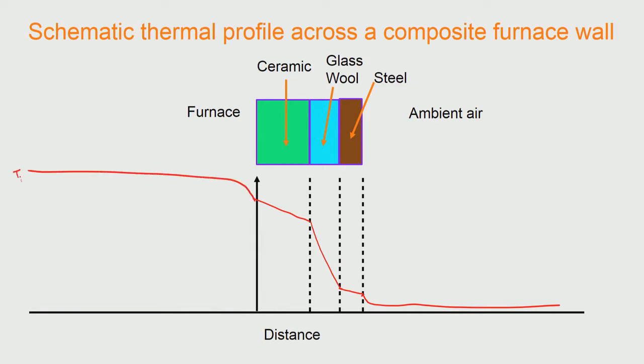Okay. So, T peak here, T infinity here, this will be the interface temperature, this is the surface temperature inside, if you like TA, and it is like TB, etc. So, we can choose these symbols as we like, but the profile is like this, and we see that the steepest temperature gradient is maintained by the glass wool, which is protecting the heat from being lost into the ambient air, and the overall heat flow is in this direction, which you can already see from the slopes.